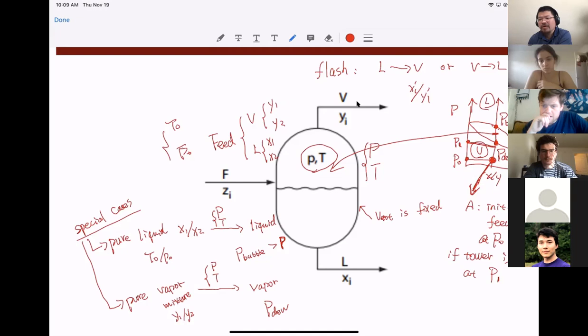Then you can see that that's not very useful. We have the feed into the tower, but the pressure inside the tower is not high enough. So there we are going to still have the still pure vapor mixture. So the only change is now we are changing the system into this point B over here, simply because the pressure is still lower than the dew pressure.